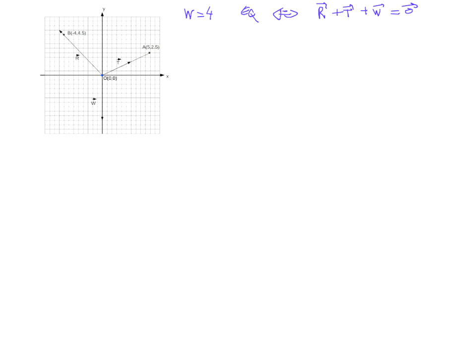So if we decide not to use a slope and stick with the position vector, let's use the same technique. We need to express those 3 vectors in component notation. W is trivial, same as before. T and R, let's use the same technique as before. We notice that vector T is parallel to position vector OA. Therefore, eT is equal to eOA. Hence, vector T is equal to its magnitude, which is what we're looking for, times OA divided by its magnitude. And this is entirely known.